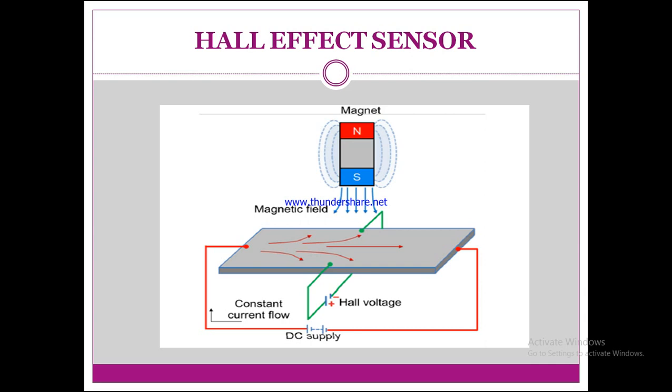When we apply a large magnetic force on this conducting plate while the plate has its own DC current, the deflection of that DC current is directly proportional to how much magnetic field we apply. This is how the Hall effect sensor is used to identify the deflection of that current due to the magnetic field.